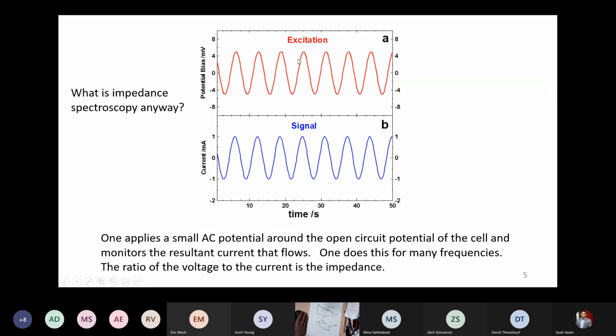So it's very important to always measure at the same state of charge if you're trying to figure out what's happening to a cell over its lifetime. And generally we like to measure at 100% state of charge and at 50% state of charge. Those are two good states of charge that characterize the cell quite well.